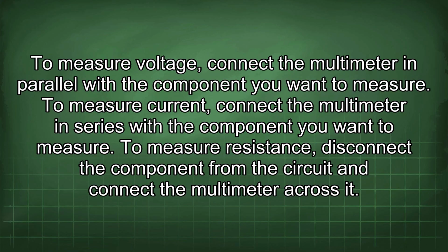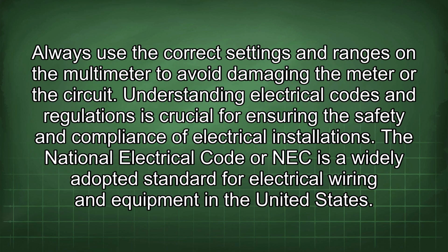To measure resistance, disconnect the component from the circuit and connect the multimeter across it. Always use the correct settings and ranges on the multimeter to avoid damaging the meter or the circuit. Understanding electrical codes and regulations is crucial for ensuring the safety and compliance of electrical installations.